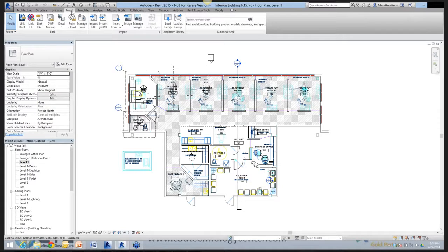you're not losing the functionality of the CAD documents that you may have had, or that because you're now in Revit you can't use CAD documents. From the Insert tab here, we have this first Link panel, and inside the Revit environment, linking is how we can bring other files into our new project. And as you can see from my screen by the colors, I have already brought in a CAD document,